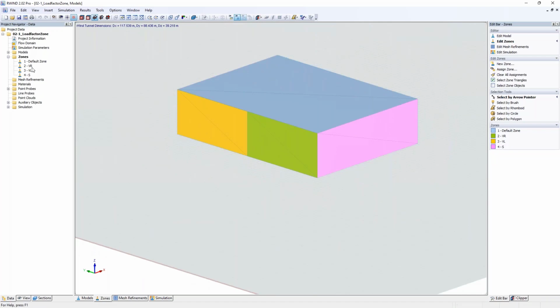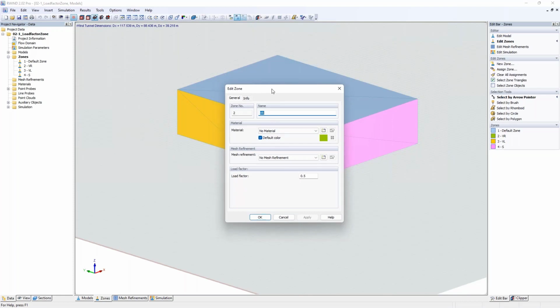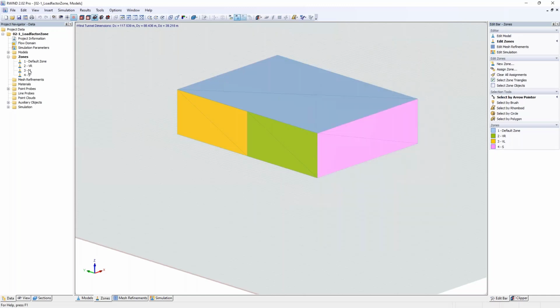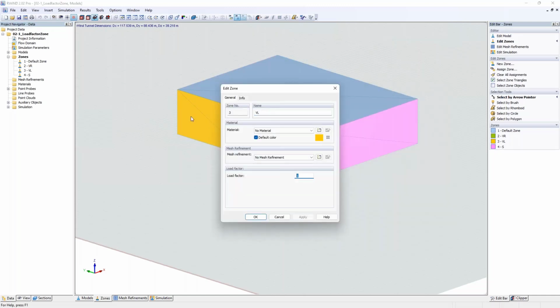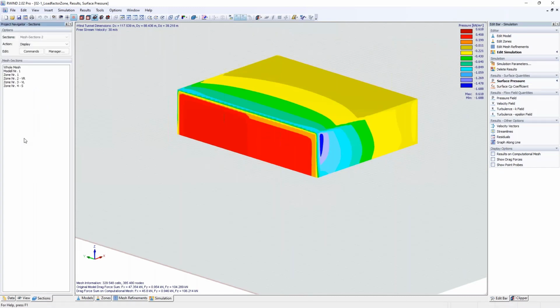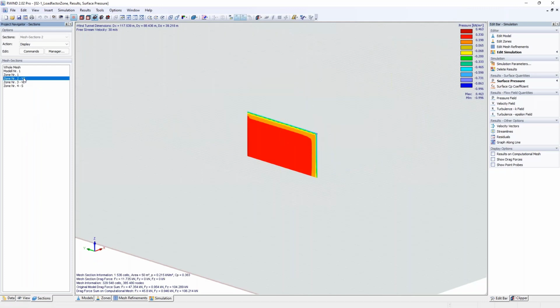And then once you have defined these zones, like having your permeable surfaces, you can just double click into the edit zone bar, and maybe you have already seen the factor in here. For my right green side, so half of the front, I've chosen that the factor should be 0.5. And compared to this, the factor on the left should be 1, so that you quickly see that it's adjusting the results. And just by chance, I have raised the sides to 2. And if you then check the simulation results, you might already see a color change in those zones. But the best thing is, of course, to evaluate them one by one.